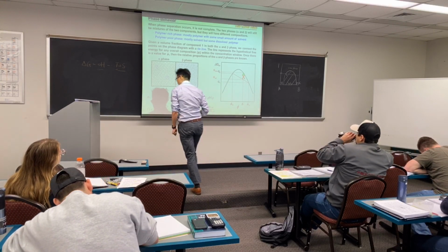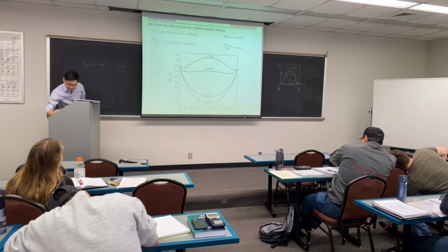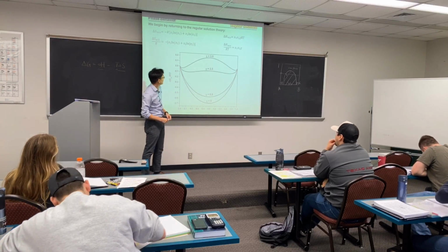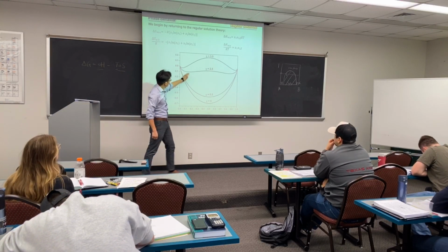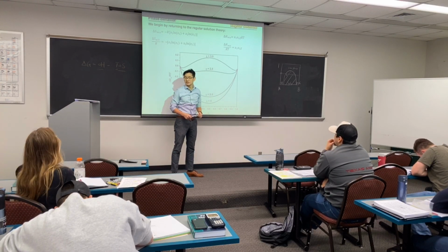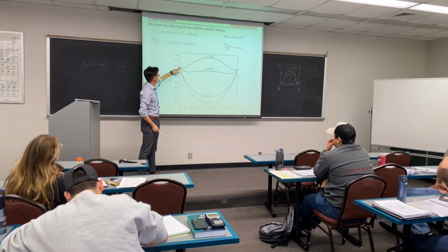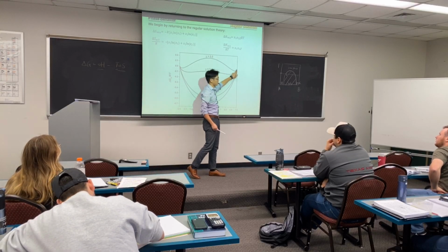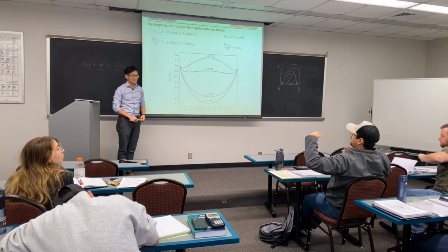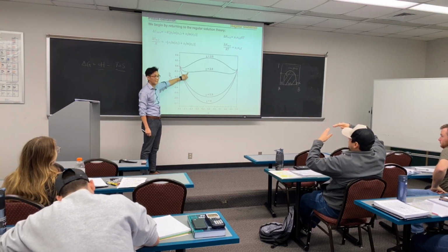But I want you to go home and think about one question. If my delta G, with respect to volume fraction, has both concave up and concave down, what's going to happen? Let's follow this chi equals 2.5. Just follow this curve. I have this behavior. Anyone want to give a try? As you're going between the low and the max and the min, you're going to hit metastable in between.